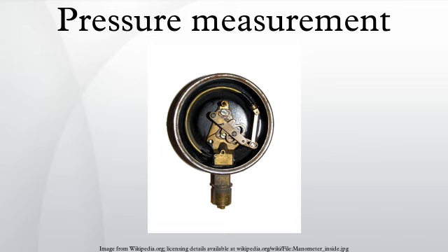Useful range, 10^-10 to 10^-3 torr. Most ion gauges come in two types, hot cathode and cold cathode. A third type that is more sensitive and expensive, known as a spinning rotor gauge, exists, but is not discussed here. In the hot cathode version, an electrically heated filament produces an electron beam. The electrons travel through the gauge and ionize gas molecules around them. The resulting ions are collected at a negative electrode. The current depends on the number of ions, which depends on the pressure in the gauge. Hot cathode gauges are accurate from 10^-3 torr to 10^-10 torr.